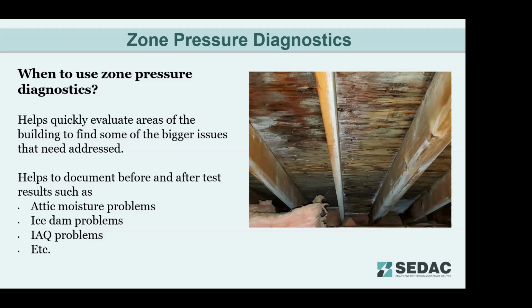We can also use zone pressure diagnostics to help diagnose problems after the building is completed. We use that to diagnose attic moisture problems, ice damming problems, indoor air quality problems. In particular, if the attic floor is very leaky and a lot of conditioned air is getting into the attic, there's a big danger of moisture problems in the attic.